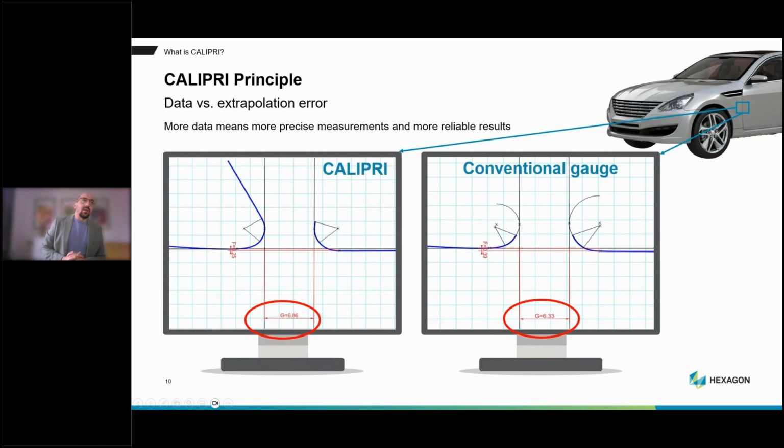This is a bit of a problem in automotive production because our radii are never perfect. Basically, there are a lot of influences on the radius in production: hemming processes, painting processes, coating processes, tool processes, everything. So normally our radius would start out with a small radius, having a more consistent, bigger radius in the middle, and then a small radius at the end. Depending on how much of the radius would be captured, extrapolation values would be different.